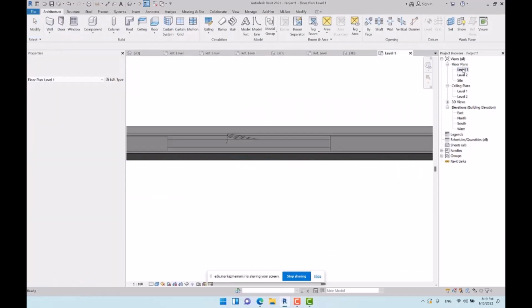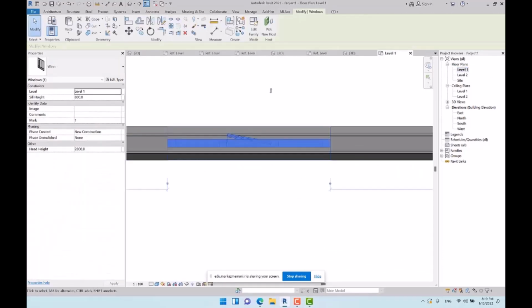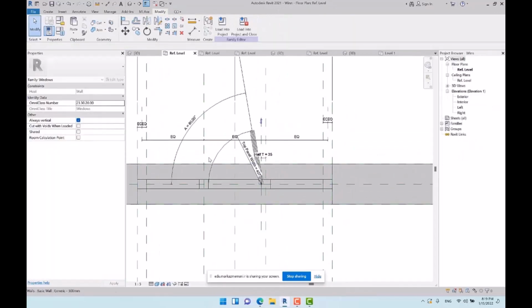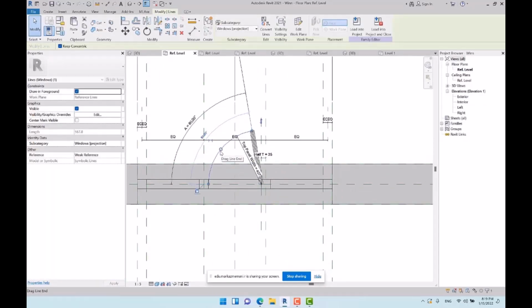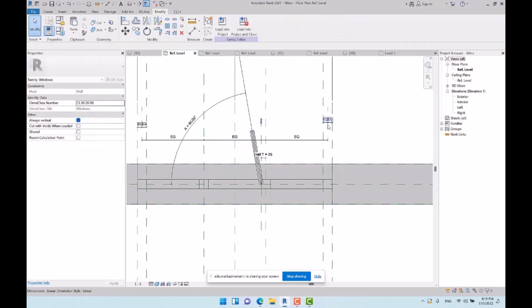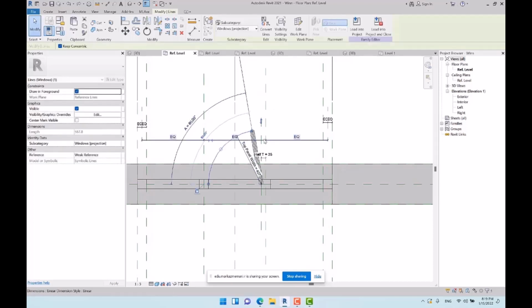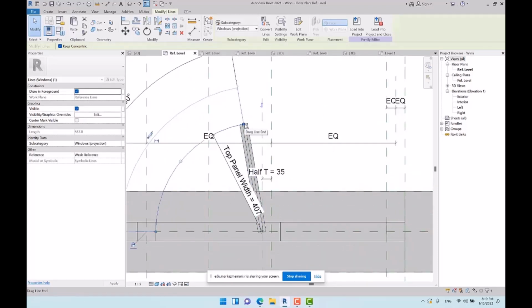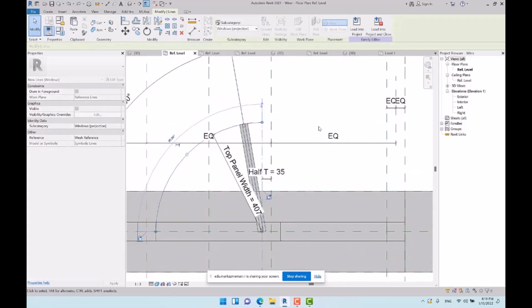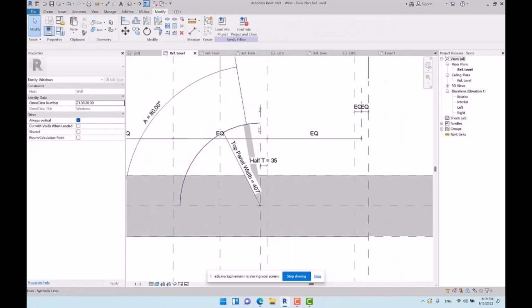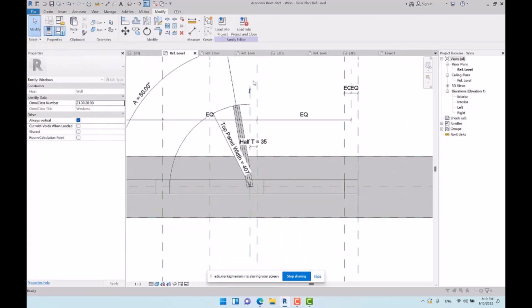Well done. But I got a recommendation. I open edit family. In my opinion, I think we should create a new family for the opening in a new template file, whose angle is controlled independently, so that we will not have problems with the zero angles. But if we want to keep the current model, we can choose to keep the door open always this way. I mean the movement of the door or the window is mentioned in the plans.